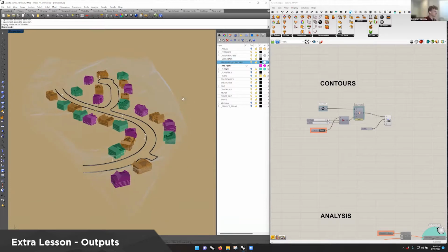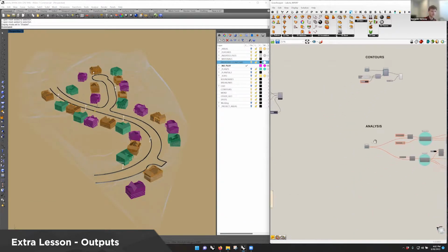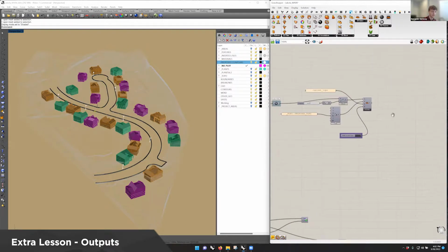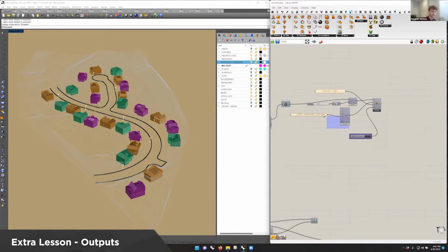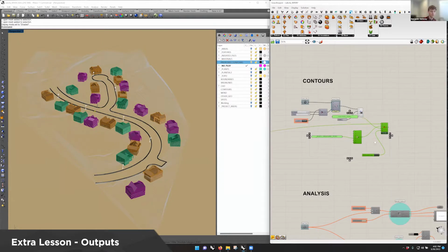Yeah. So contours, again, you can set up the same workflow for contours that you have for any type of geometry using the Elefront workflow. So I could actually pull these pieces over here, and I just did. Once you start dragging something in Grasshopper, if you click Alt, it will copy it. So that's a nice little hotkey for you all, an easy way to copy things around.